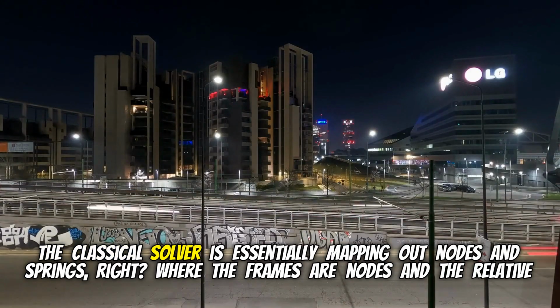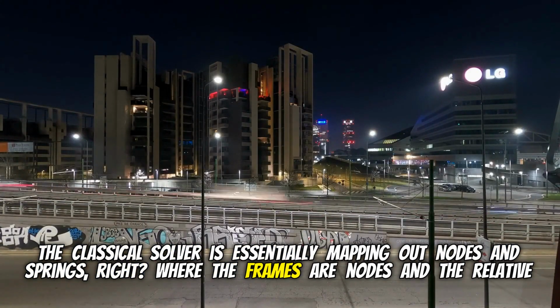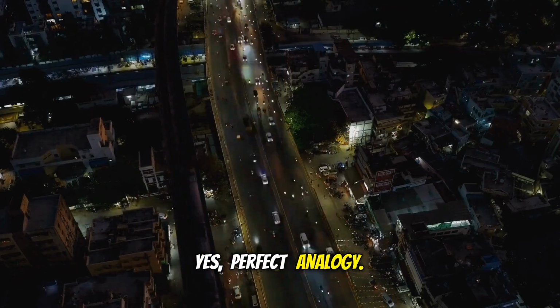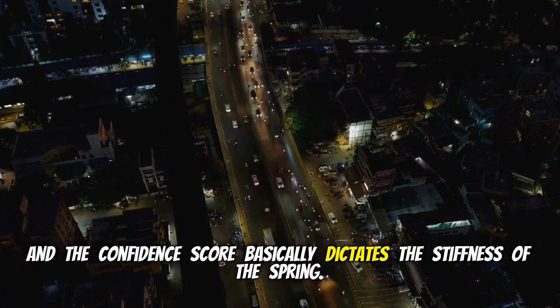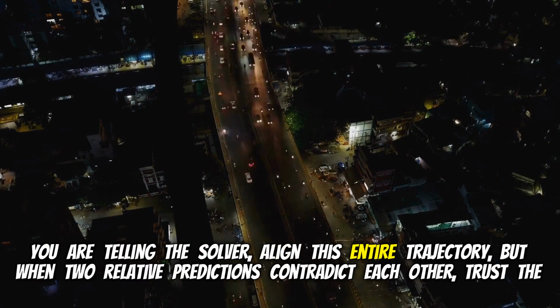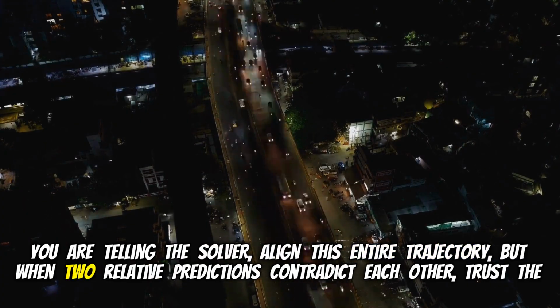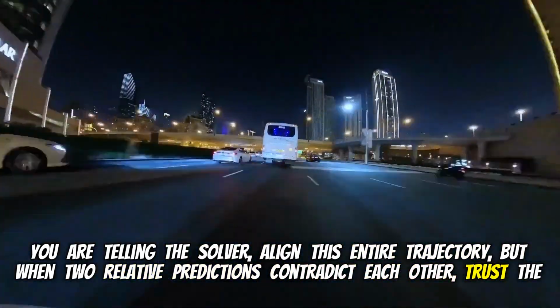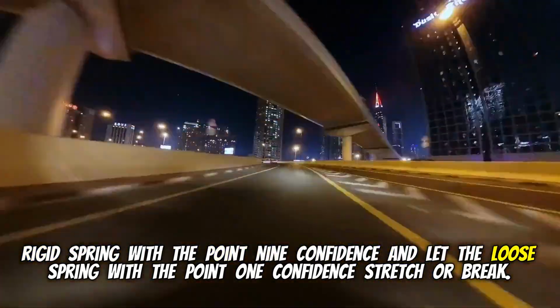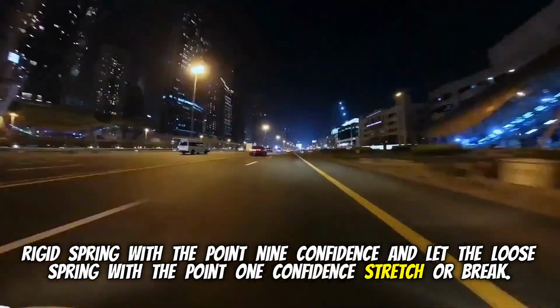The classical solver is essentially mapping out nodes and springs, right? Where the frames are nodes and the relative poses are the springs connecting them. Yes, perfect analogy. And the confidence score basically dictates the stiffness of the spring. You are telling the solver, align this entire trajectory, but when 2 relative predictions contradict each other, trust the rigid spring with the 0.9 confidence and let the loose spring with the 0.1 confidence stretch or break.